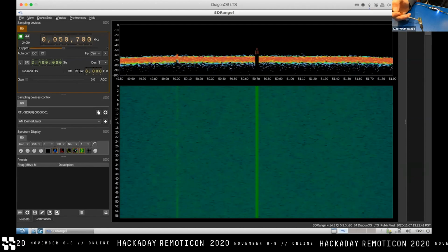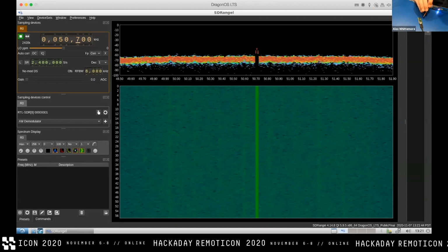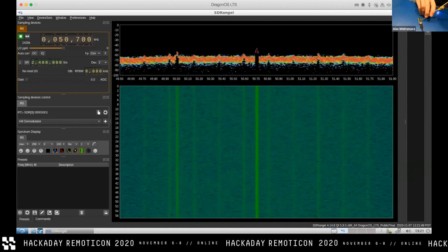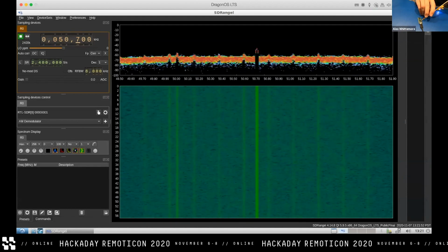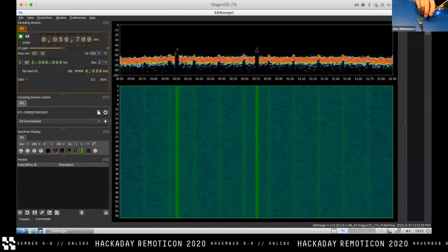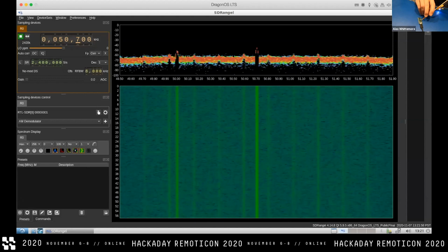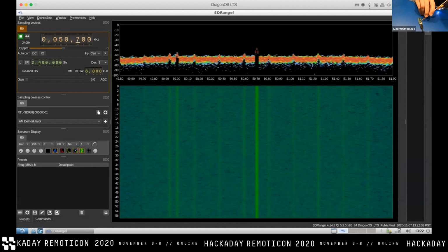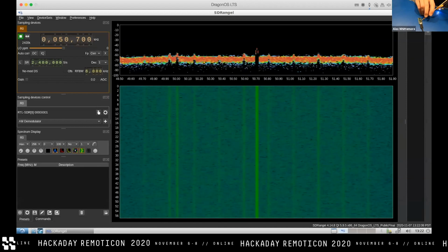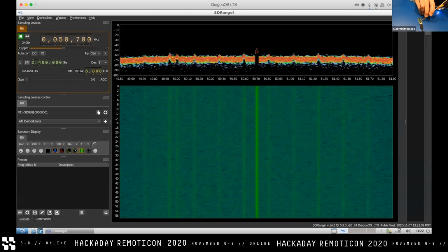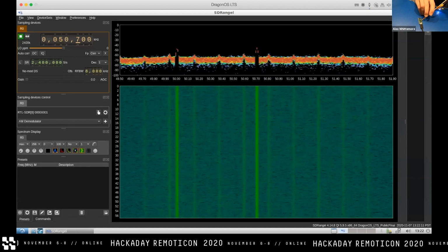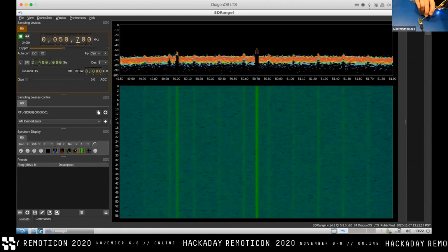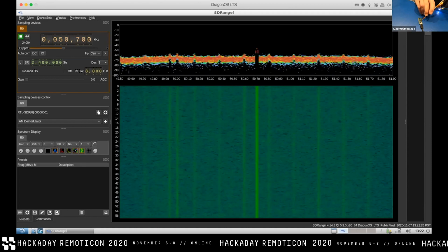And over here, we see the signal a bit, but then let's do that IO pin trick where I put the probe basically like a projected shadow of the trace that it's on. If I move around, ooh, I start to see a lot of stuff going on. But there is a pin somewhere on this side of the board, right about, this is where having the buzzer, actually, I don't know that it's worth the cost, but it's certainly nice. There's a pin somewhere right over here, right about there, maybe? Something like that. That looks a little bit like something going on over here is probably what we're after.